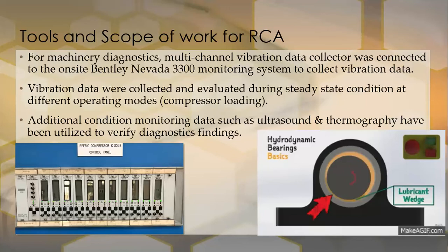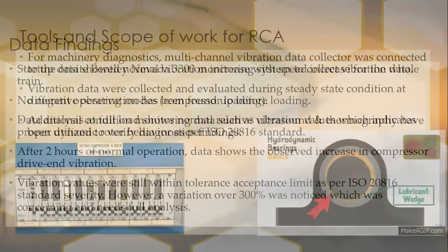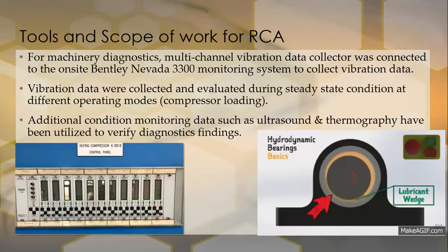Vibration data were collected and evaluated during steady-state conditions at different operating parameters and operating modes of compressor loading, via changing the suction pressure level and the flow level. Additional condition monitoring data such as ultrasound and thermography have been utilized to verify diagnostics and findings.